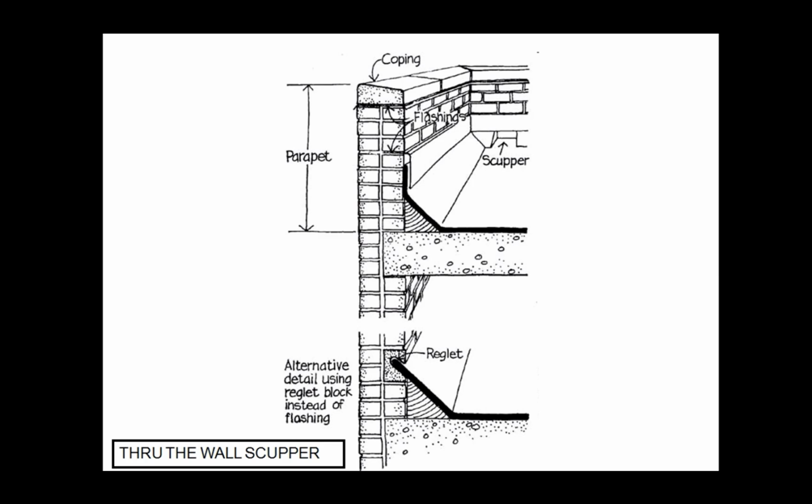All right, here's a nice detail. I probably should have put this a little bit earlier in the lecture, so you could see what the details are here. That top layer of stonework is called the coping. You have various flashings which you use to layer and overlap on the side of the parapet wall there, which is the extended wall over the roof element. Okay, so you see the concrete roofing there. A parapet is built around your roof. As you can see the details of how it's in there.